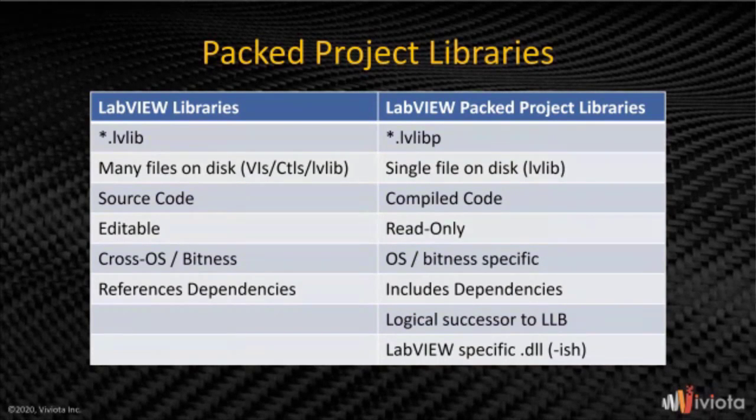But in reality, this is closer to a LabVIEW specific DLL, where you're packaging all of these library functions into a single file and it can then reference it from LabVIEW. So it is compiled, so that means it's read-only. And the other aspect of this is that it's actually OS and bitness specific. So if you compile a PPL, it's only usable for the LabVIEW bitness and the LabVIEW OS you compiled it for. So you might have to have multiple versions of the same PPL compiled for different OSs and bitnesses.